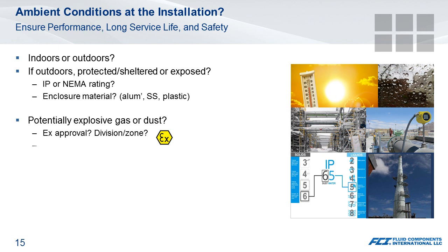And sometimes overlooked is whether the sensor and transmitter should be separated from each other. With consideration, is there access to the transmitter electronics for easy wire up, readability if there's an onboard display, service access ease, and high temperature applications? You certainly don't want to put an electronics transmitter right next to a pipe that's running at 700 degrees Fahrenheit.